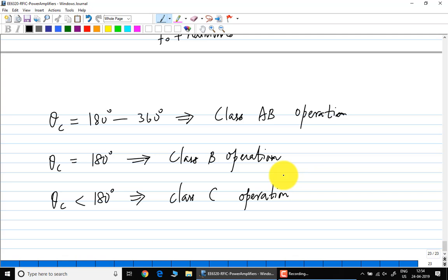Now, how do you take a linear PA, the structure that we have built, and convert it into a class B PA? How do I do that? The minute you do a push-pull configuration, your output is not biased at VDD, so you can't swing so much. He's talking about a push-pull configuration coming from low frequency amplifiers such as audio amplifiers, etc. You can design the same thing, but not so easily. Technically, if you bias the inverter carefully, that can act in a push-pull configuration.